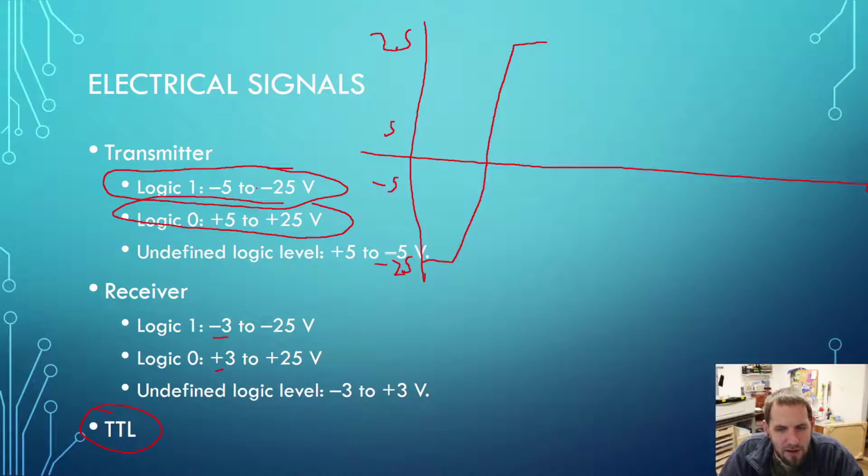So somewhere between, say, 15 or 20 volts or whatever it is that it's being supplied with. I think 12 volts is a very standard voltage to be used. Most computers, like desktop PCs at least, have a 12 volt power line coming off their power supply. So it's a very standard voltage that will be used with RS232. But again, anywhere within that range. And if you're going to be sending over a much longer distance, the higher your voltage, the better off that you will be.